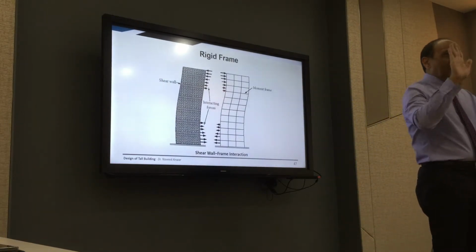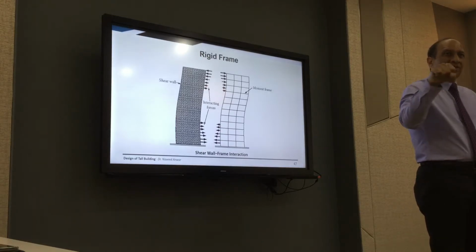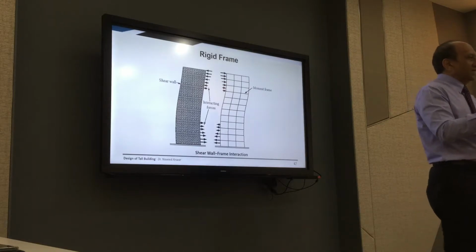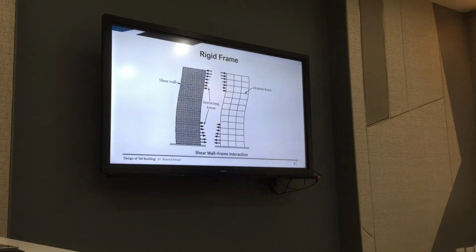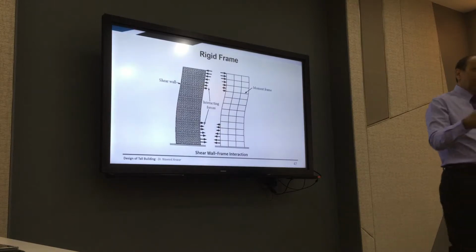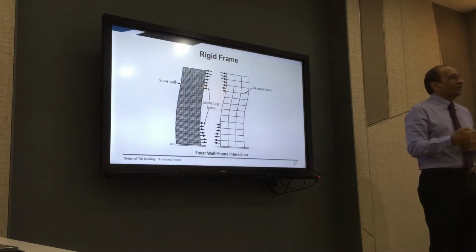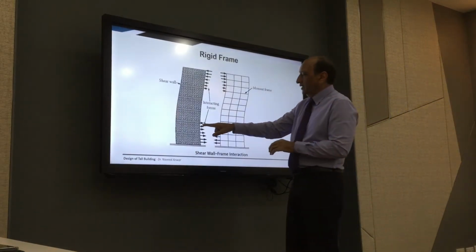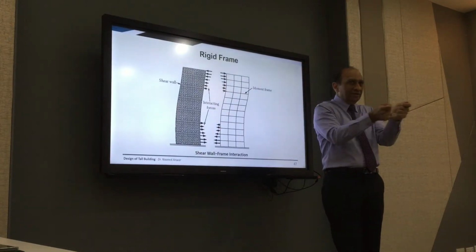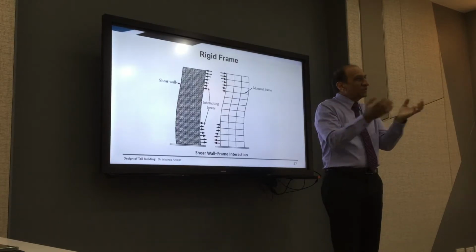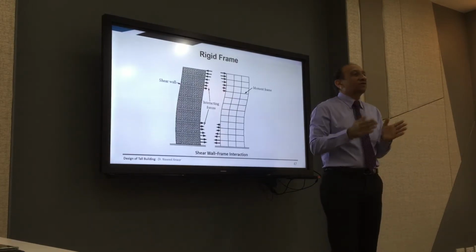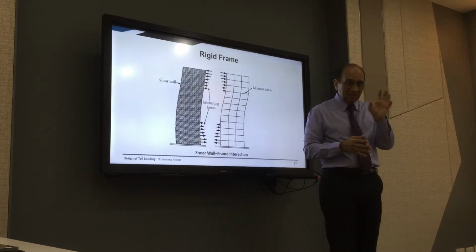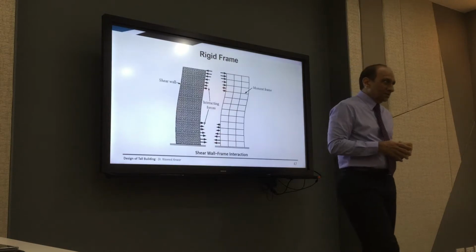So when you put a frame and a wall together, they start to pull and push on each other. This is frame shear wall interaction number 1. There is also frame shear wall interaction number 2, which is the outrigger effect, which I will come to later. So if you just connect one frame to the shear wall just by very thin members, it will still reduce the total deflection because the deflection pattern is opposite. So this is good, right?